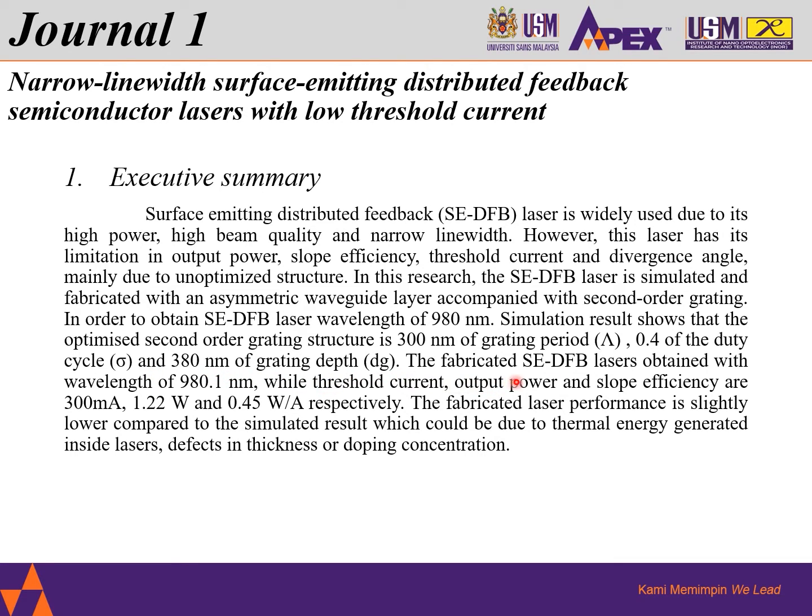The fabricated SEDFB laser obtained with wavelength of 980.1 nanometer, while the threshold current, output power, and slope efficiency are 300 mA, 1.22 watt, and 0.45 watt per ampere respectively. The fabricated laser performance is slightly lower compared to the simulated result, which could be due to the thermal energy generated inside the laser or the defect in thickness or doping concentrations.